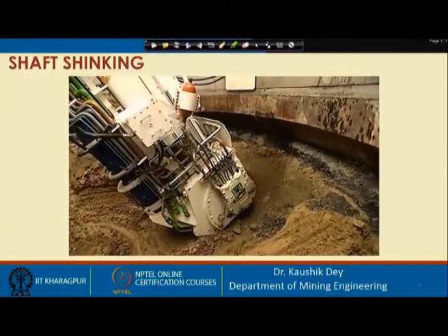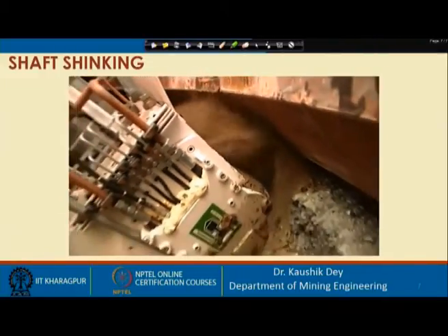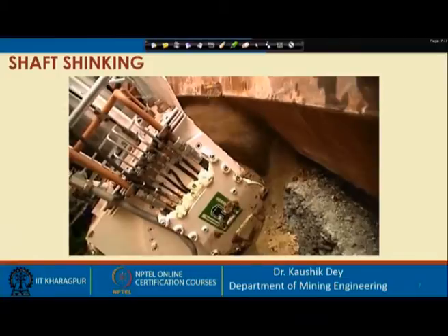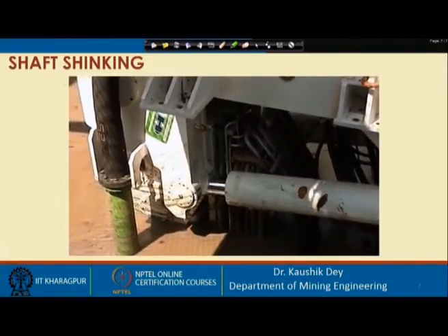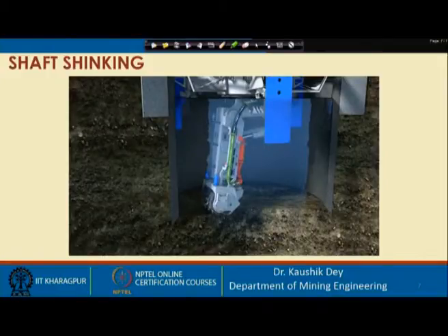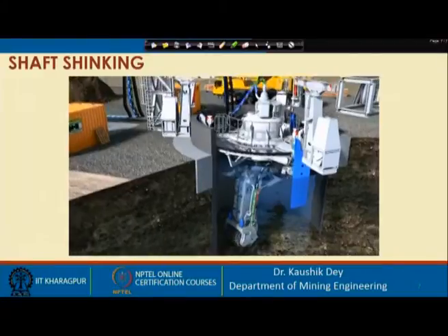After creating an opening up to a significant depth, the lowering of the sidewall supports has to be carried out. A slurry circuit transports the excavated material from the shaft out to a slurry separation plant on the surface.